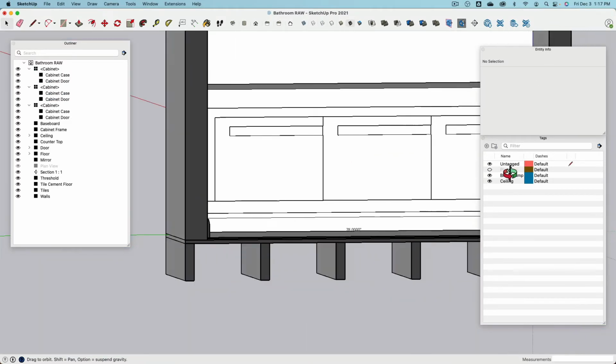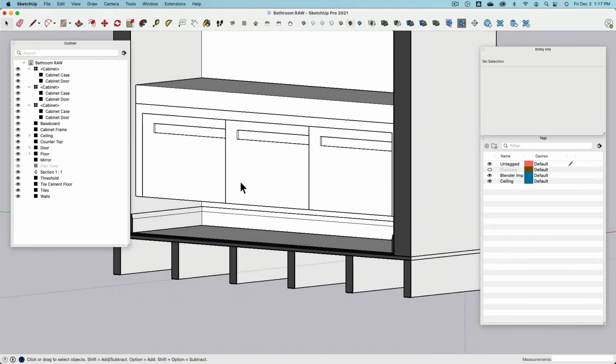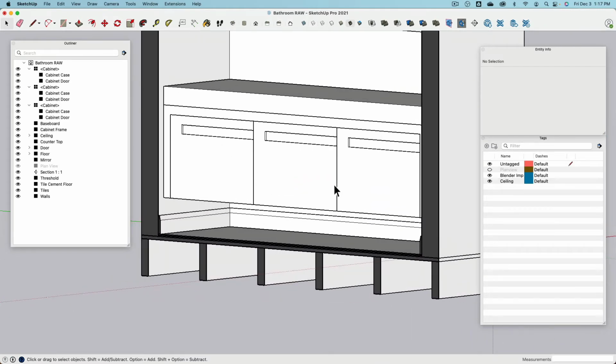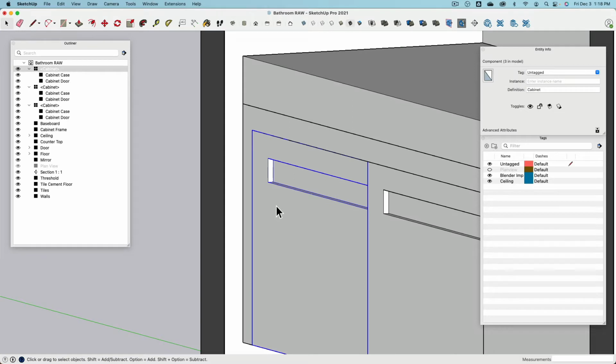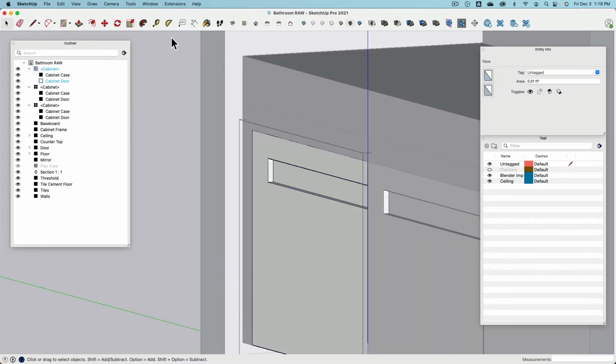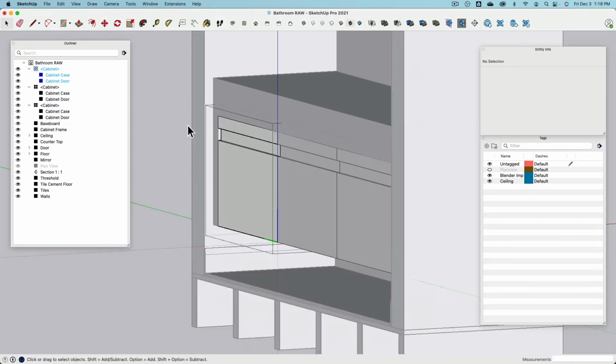Shift E, and you see they all have exactly the same design. If I want to have this to be on the other side and here in the front cut through, then actually I will have different components. A component for the left door, a component for the right door, a component for the front door. And in the back, the casing is one component because it's shared. In my case here, I make one component because the group elements inside are always the same. So here, I go back, editing this face and remove it.